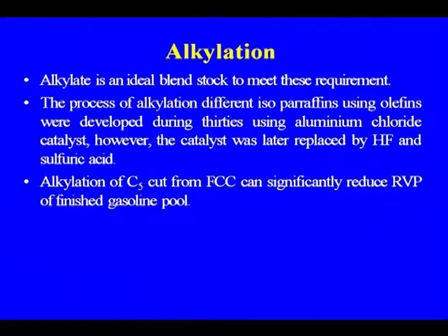The process of alkylation of different isoparaffins using olefins was developed during the 30s using aluminum chloride catalyst. However, the catalyst was later replaced by sulfuric acid and hydrofluoric acid. First it was the hydrofluoric, and because of some problems, which we will discuss when we compare these catalysts, sulfuric acid and hydrofluoric acid, and because in case of hydrofluoric acid a lot of corrosion problem was there, now the shift in the catalyst is from HF to solid acid catalyst.